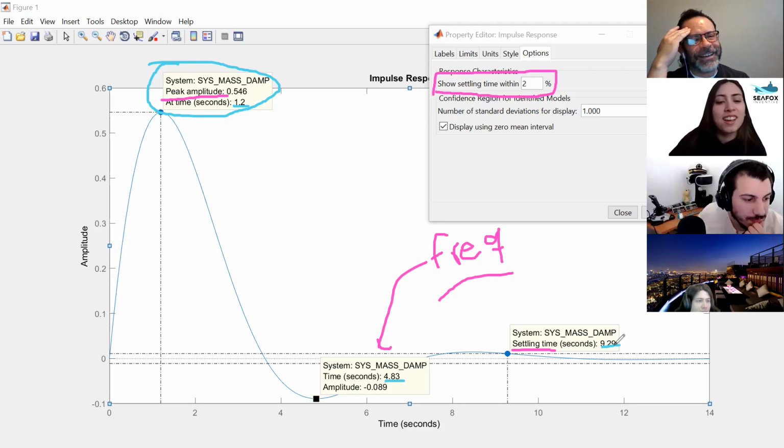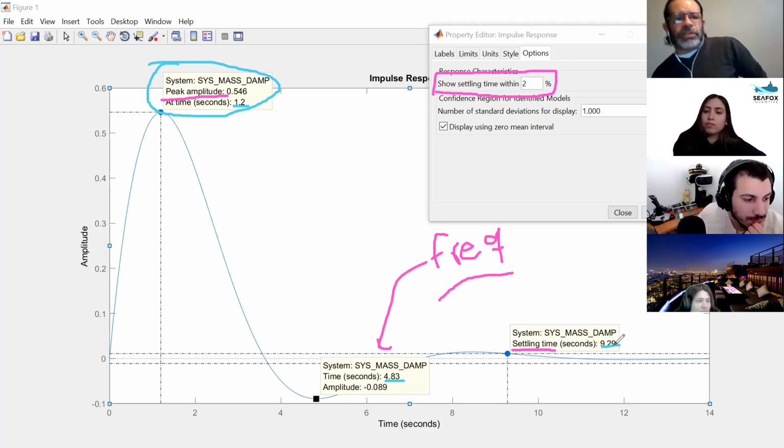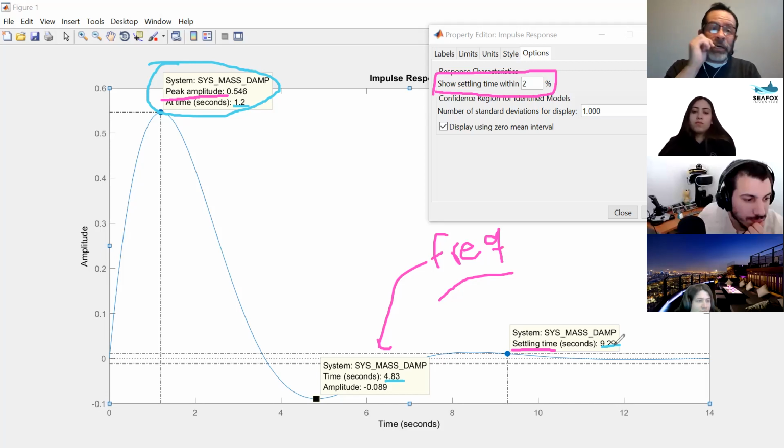Just confirming. Yeah. I think it is slow because it lasts like 14 seconds, which I think is a lot. Yeah, and the settling time is almost 10 seconds. 10 seconds is an eternity. Now, is it slow? With regards to that, I think your assessment is correct, Marianne. It's slow. But maybe we want it to be slow. We don't want a very, very quick reaction.